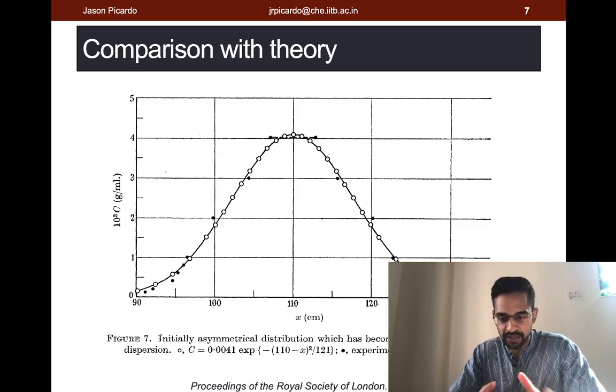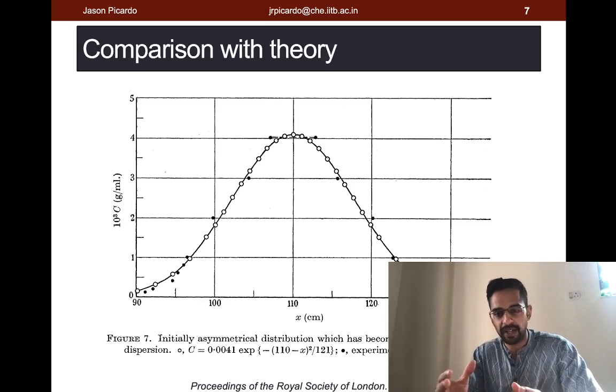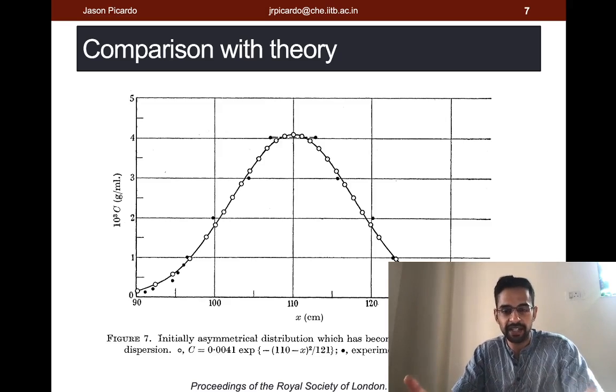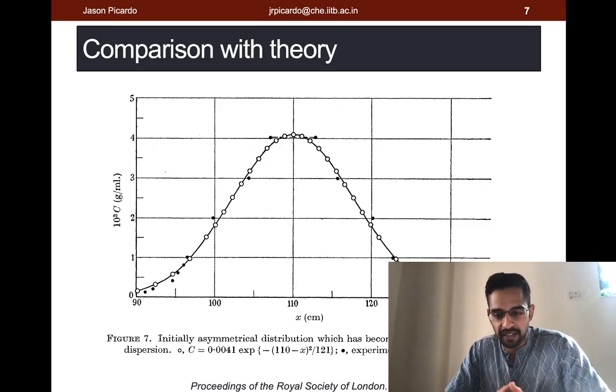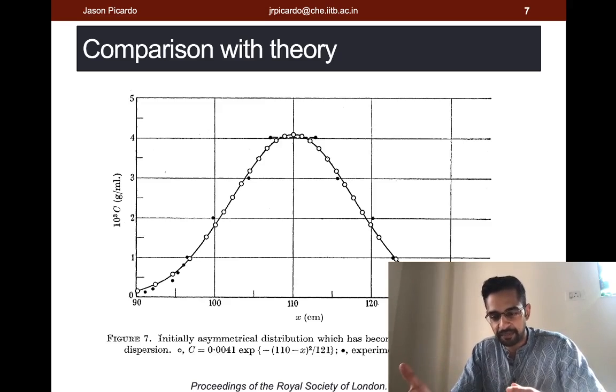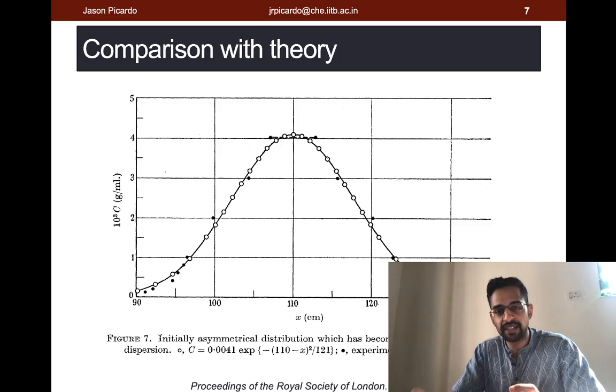So having now studied the problem of laminar dispersion, it's natural for us to consider the same method applied to the non-ideal plug flow reactor, which is something that as chemical engineers we have studied previously in reaction engineering courses. In those courses, we would have looked at non-ideal reactors empirically. So typically what's done is people motivate the introduction of a non-ideal dispersion type model for a PFR from really Taylor's experiments and others on laminar dispersion. But here we will see how we can obtain a precise model, in the next lecture.